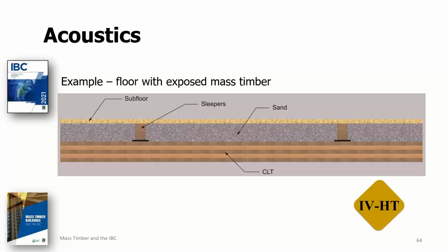One of the characteristics of mass timber is that it has a high strength to weight ratio when compared to other panel and slab type construction materials. It weighs significantly less than, say, a concrete slab of the same thickness. With acoustics, more mass typically means better noise control. For comparison, a typical 6-inch thick concrete slab weighs approximately 80 pounds per square foot and has an STC rating of about 53, but a 7-inch thick CLT panel weighs about 18 pounds per square foot and would have an STC rating in the low 40s. That's if it's bare. Again, I'm talking bare panels here.